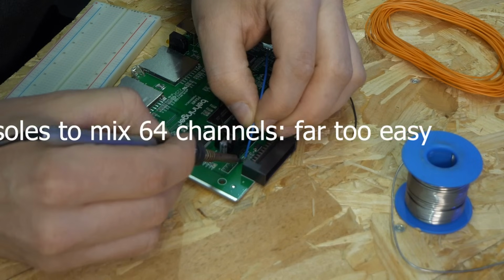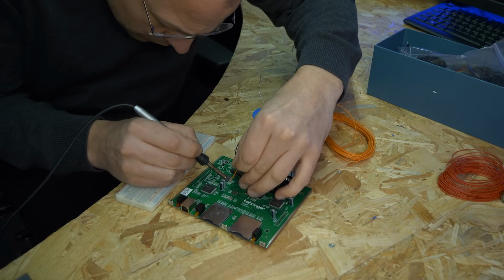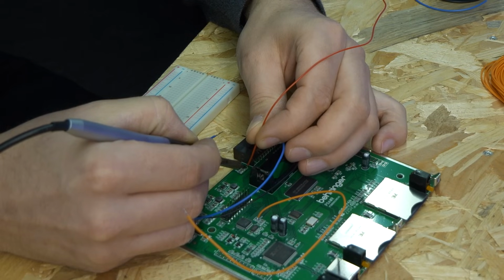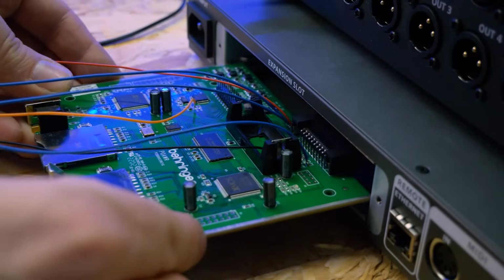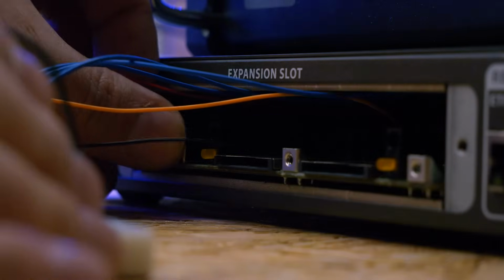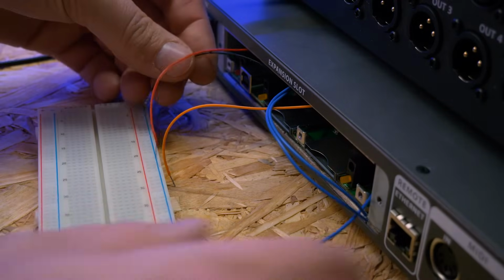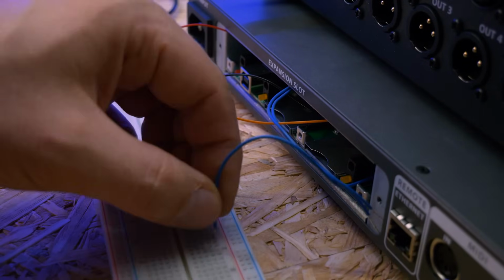So solder on the test leads. Here we need the 2 control lines and a ground connection in any case. The 4 I2S or TDM-like signals would be a good idea if they are such signals at all. The X32 displays the name of the respective card. Since the Schematic U-Track32 does not display its own name, it is probably not the name that is transmitted in plain ASCII, but some kind of ID that the X32 can then retrieve from its firmware.